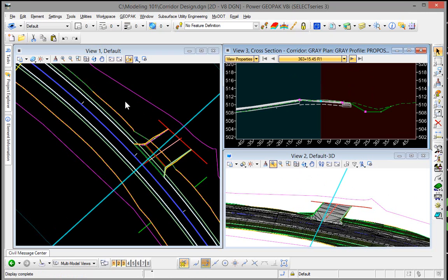But if I'm coming in and adding key stations or something maybe in my design view, or targeting my edge of pavement with parametric constraints or point controls, I don't necessarily need my model and my dynamic sections and my profile view open, so I may close those, and that will help optimize things as well. Just remember that these dynamic views require additional processing to show those views active in real time, and so there's nothing wrong with having them open. Again, it's just another tip on things to consider, especially when you have very large projects, several miles long.